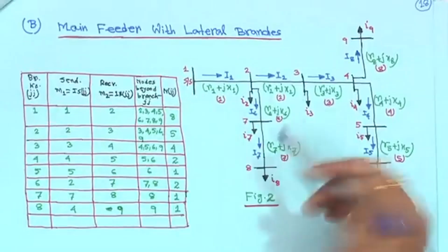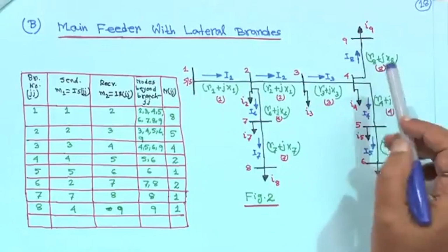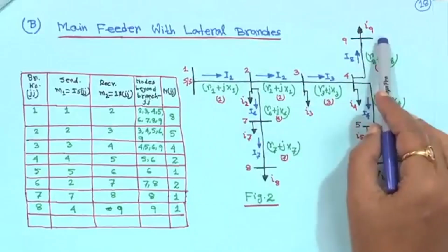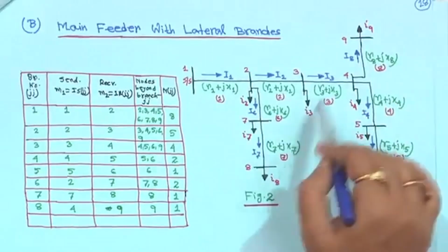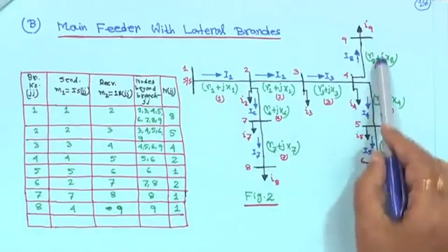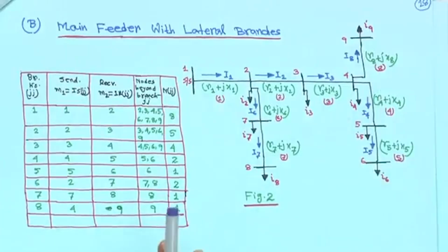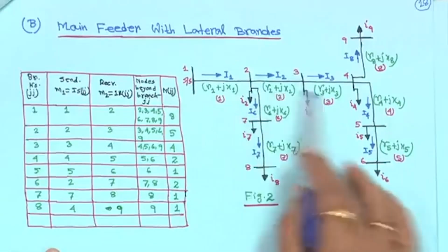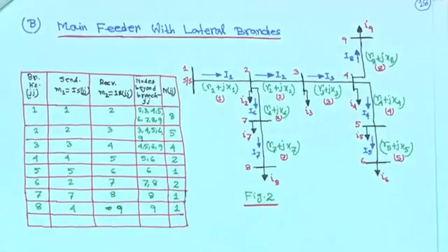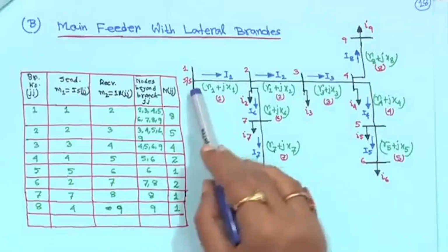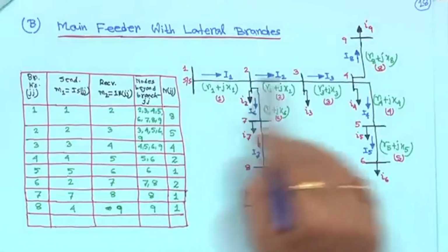So, the way you want, you can number, it is not a problem. Just try to maintain that the number should be between 1 to 9. After that, wherever you put those numbers does not matter, because you have a 9 node system. The only thing is the connectivity; according to the connectivity you have to form this E matrix, which is important.